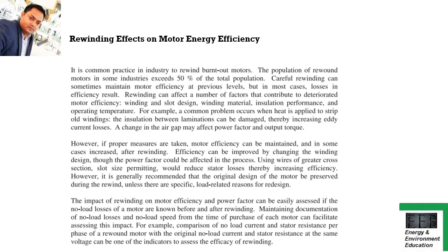What happens basically is that once you rewind the motor a number of times, motor energy efficiency goes on decreasing. The second effect is that once you rewind the motor, it starts consuming more and more energy, and it also impacts the electrical bill. So it's more important that you buy a new motor than stick to a rewound motor. As an auditor, we also recommend to our client that please do not rewind motors a number of times, because as you rewind the motors, motor efficiency decreases, and this also leads to an increase in the energy bills or electricity bills.